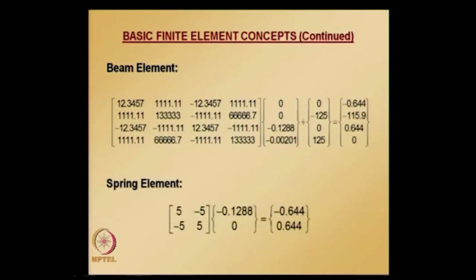Similarly for the spring element. Using either these values or the previous values that we calculated for moment and shear, with the corresponding sign conventions, or the values that we computed for internal moments and shears using the nodal values a while back, you can draw the free body diagram using the appropriate sign conventions.